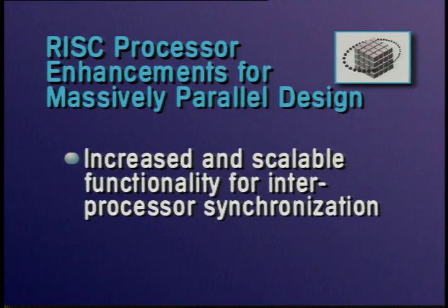Interprocessor synchronization must be fast and scalable. Typical RISC microprocessor designs anticipate only very moderate numbers of processors working together within a workstation. Techniques used are often bus-based, such as the popular bus snooping protocol. Due to very real physical constraints, these schemes do not scale well beyond about a dozen processors. Software and I/O-based synchronization protocols used in workstation cluster organizations may scale to large numbers, but fall far short of our goal for providing single microsecond or less global synchronization latency.